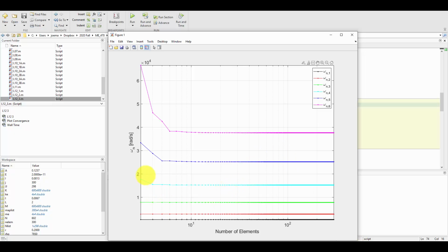All right, so by I here, we see that from bottom to top, the first natural frequency up to the 6th natural frequency follows the pattern that we've been seeing, is that the order of convergence is the same as the order from lowest to highest natural frequency in our system. So at least relatively here, the first 3 natural frequencies are very flat, and they remain flat as we add more elements. The 4th natural frequency takes more elements before visually at least it's converging, and then the 5th and then the 6th takes the most elements before we see that convergence.